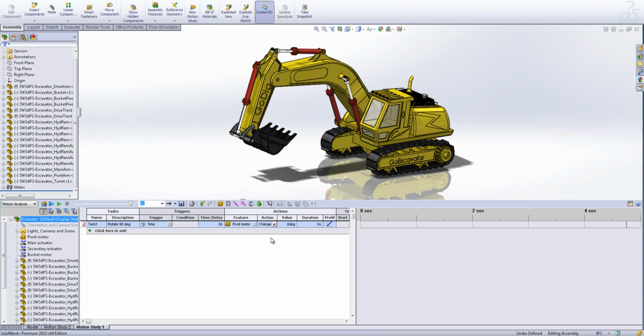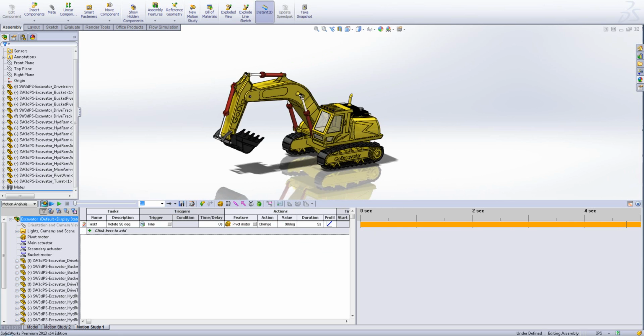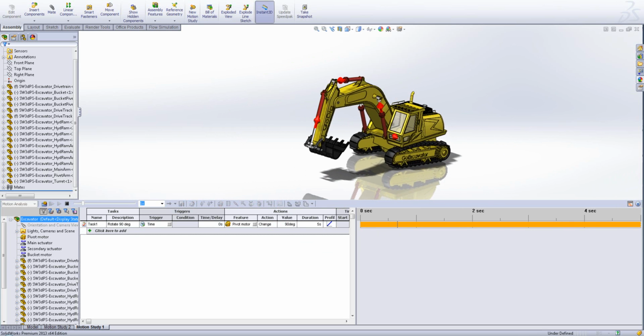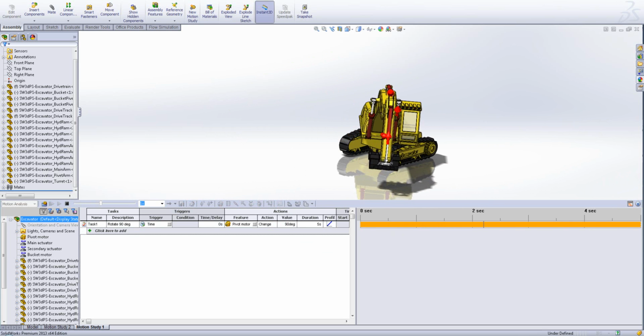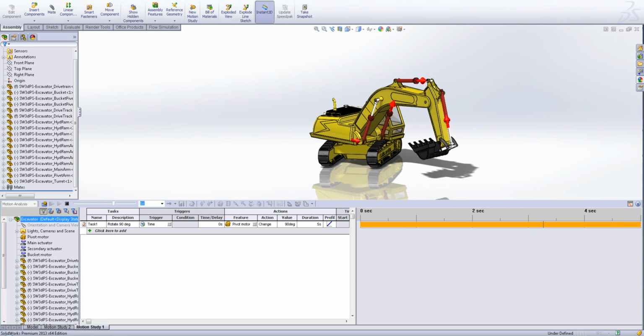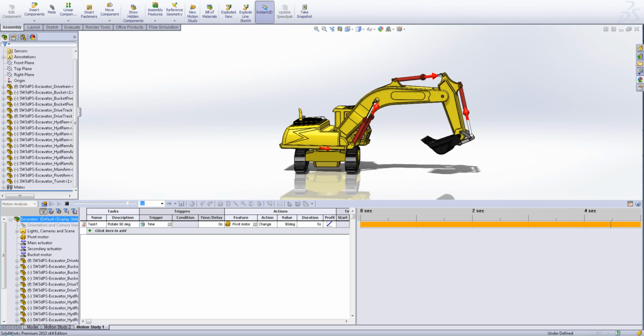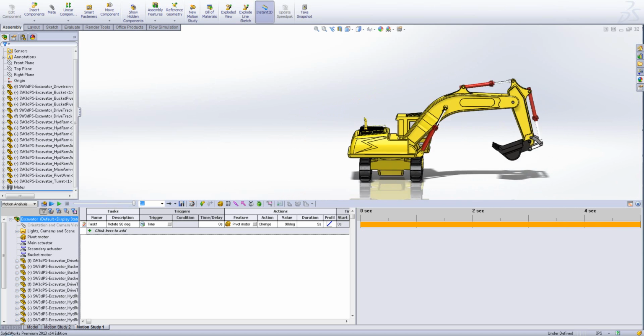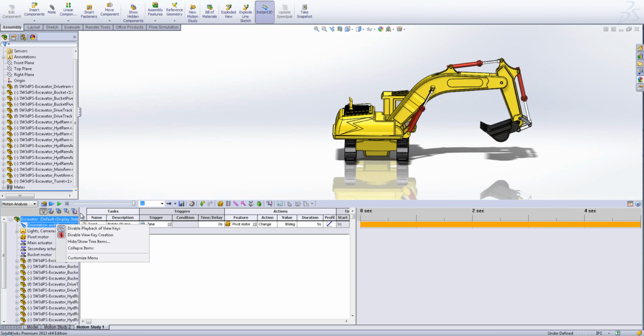specify the action to change the current value of the servo, by a value of 90 degrees. In this case, we'll make it a long sweep over the course of 5 seconds. So now let's ask SolidWorks to calculate that and see what we get. Like so. And that is it. That's the outcome of our initial setup.